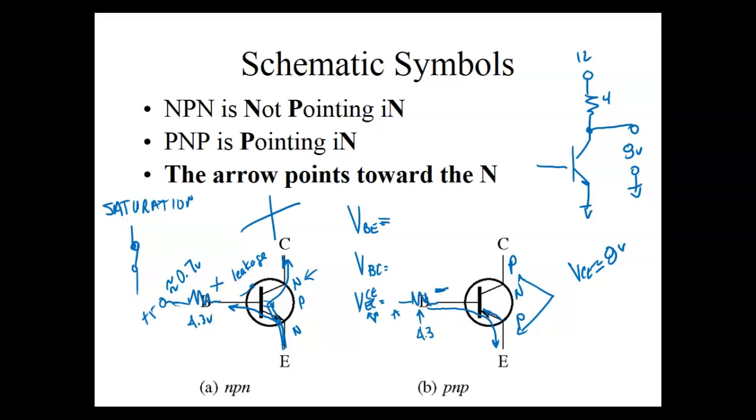How much energy do you get off the antenna on your car coming into your radio? Almost nothing, right? But yet we have these 500 watt amplifiers we can put in our car. Why? Because we can take a real small signal, bring it into a transistor, and get a lot of gain out of it. Now, if we operate it between saturation and cutoff, this thing acts like one of these.